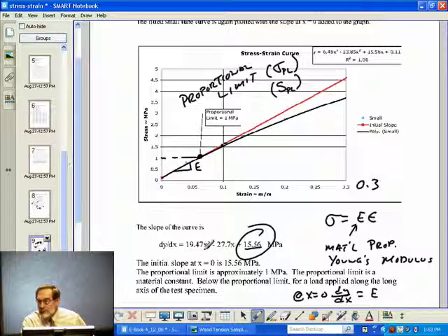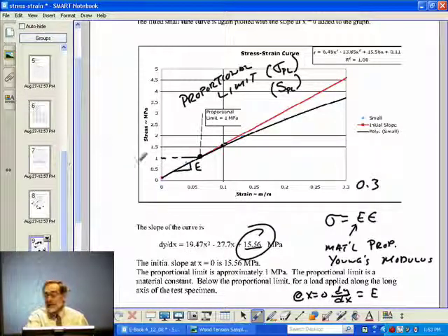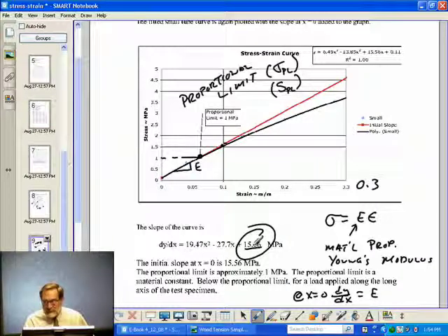fundamental material properties. And we can actually measure the strain on a real piece, and then come back and say, well, that stress is such and such because I know what the E is. Steel has an E. Aluminum has one, but it's about 1/3 of that of the steel. It's interesting to also note it has about 1/3 the density.